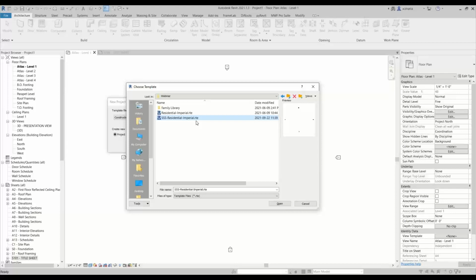That file has all the families that I need to use for MWF. I also have all the hardware I might need, the marker lines, the horizontals, and the templates created, all of them already located in that file. They're available for me to use for any new project from now on because I saved it as an RTE, okay?